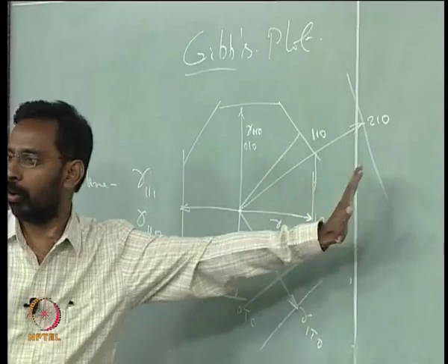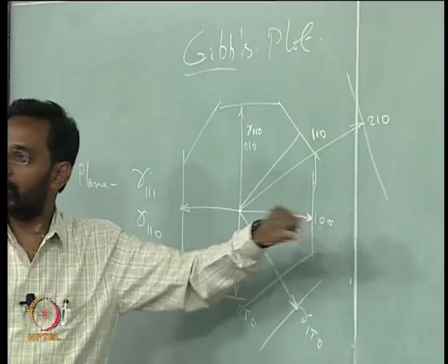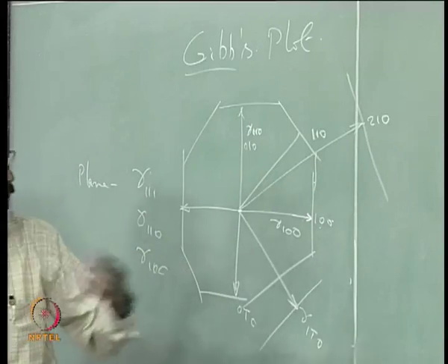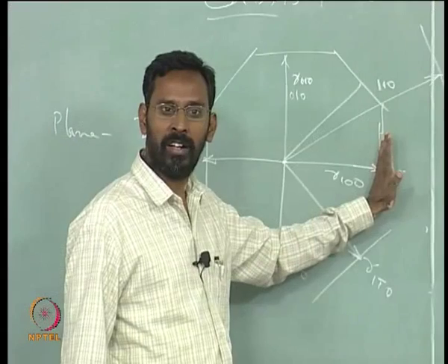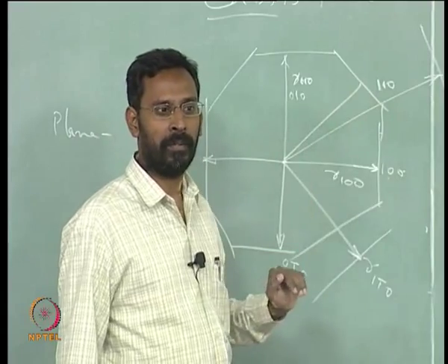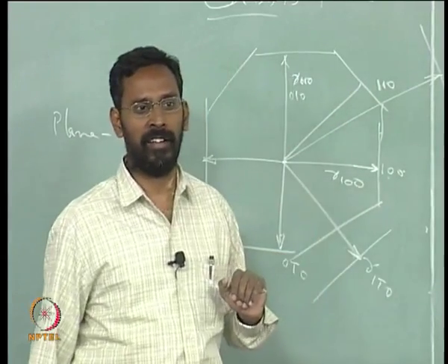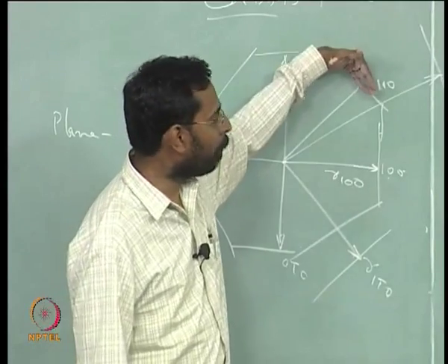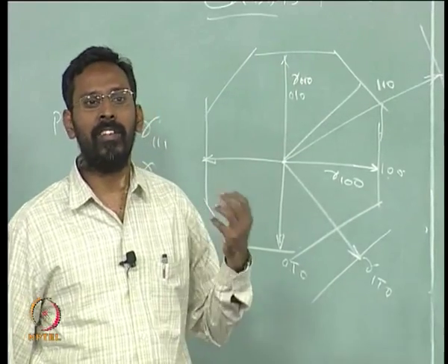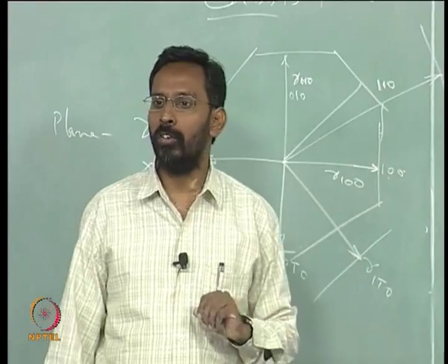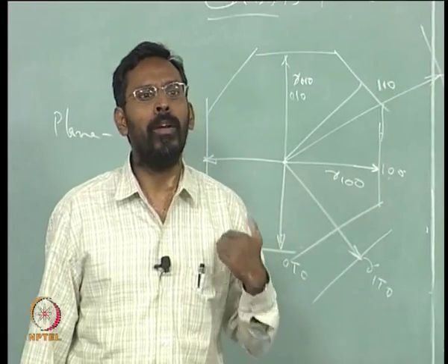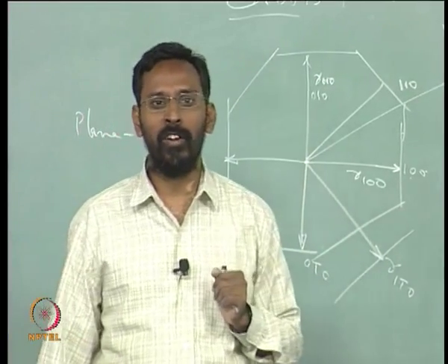Whenever it has to grow, the rate depends on how many atoms the plane needs to fill up that plane. When that plane is filled, it grows by a small delta x. So, if a 110 plane needs fewer atoms than a 100 plane, the 110 plane will move faster than the 100.